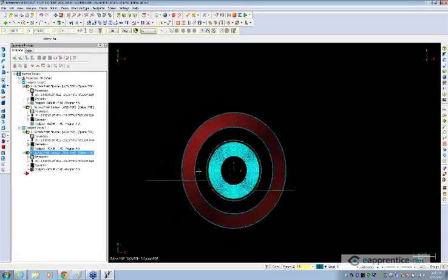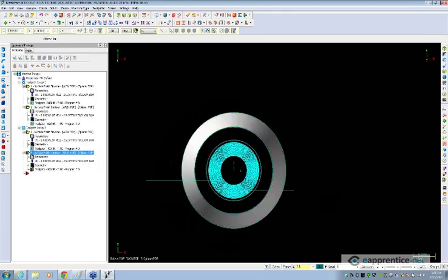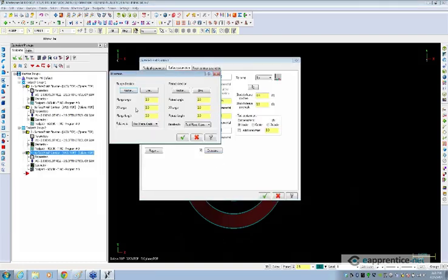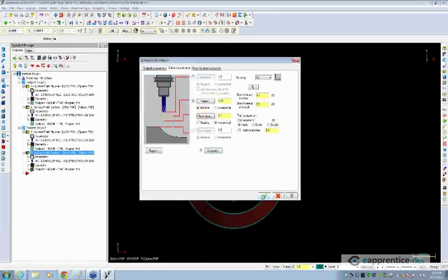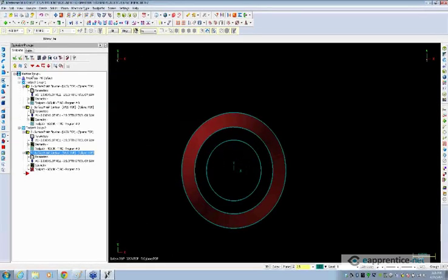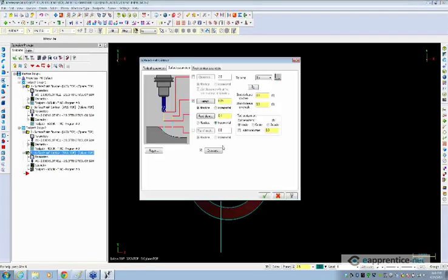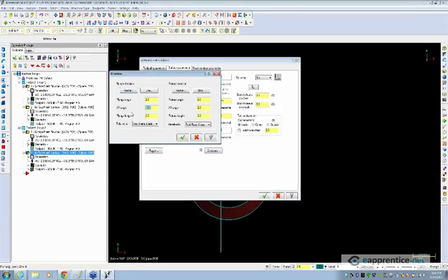But if I do that, now I can see I've got a plunge length going this way for my entry of 3 inches. Here's my exit. So what I'm going to do is now adjust that direction XY angle until I get the entry that I need. So there's 0. There's 90. I know 180, 270 is going to be straight up that way. So let's try like 240.